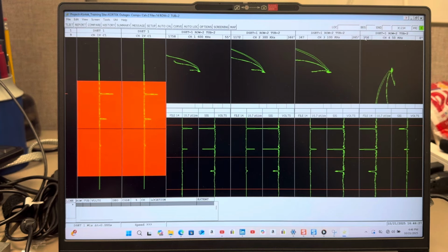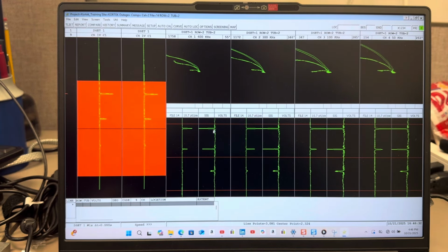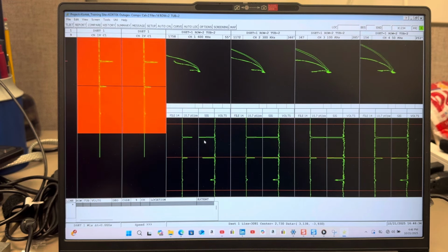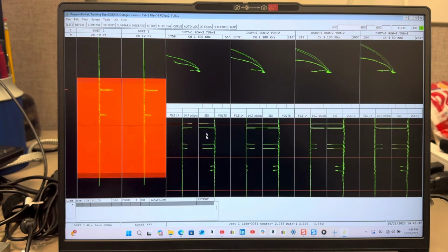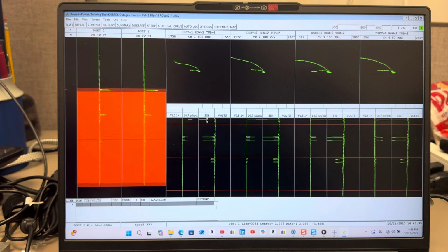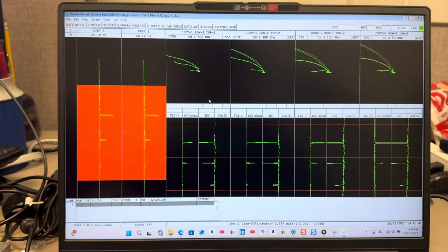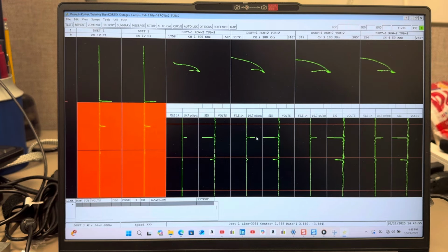It only looks noisy if you've got it spanned too hot. Now the goal would be to have probe motion or noise set horizontal. Well, here you don't see much noise at all, do you? So to try to get these things all set the same, I'm going to put that shallowest, this is an 8/1000 or 8 mil deep EDM surface breaking notch, I'm going to set that down to like a couple degrees on all the channels.